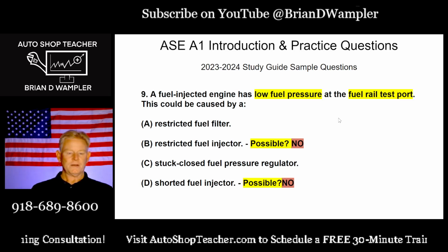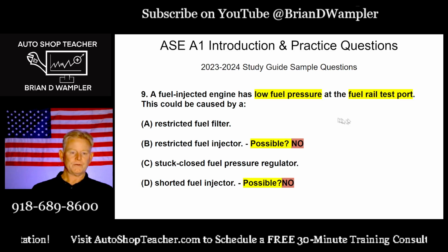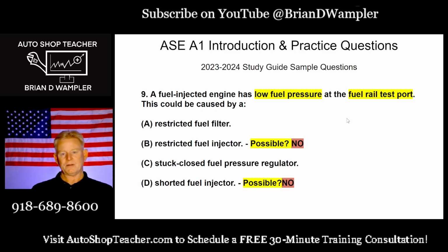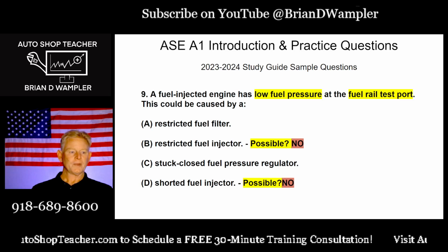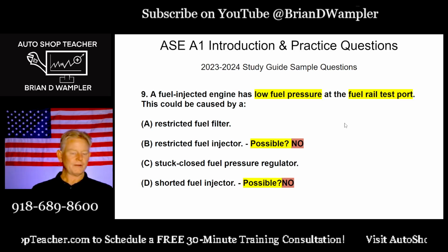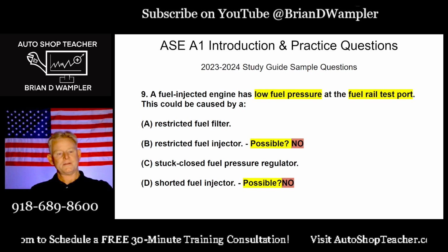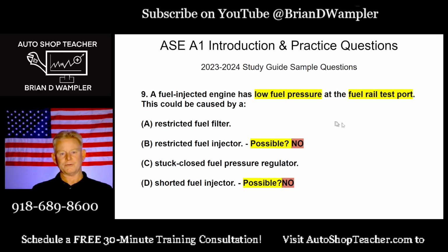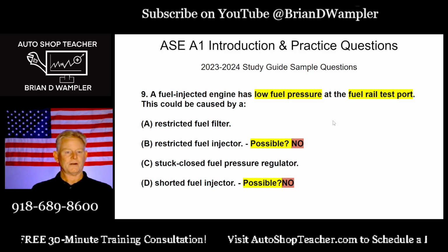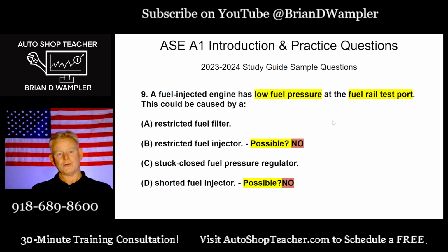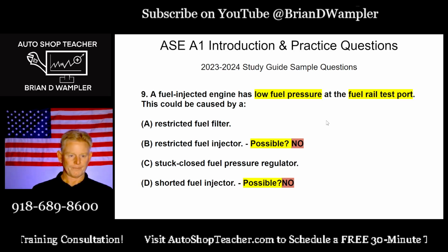That's going to cause fuel to possibly not make it into the cylinder, to the combustion process, but it's not going to cause the fuel pressure, the supply to the whole fuel injection system, to be low. Okay? Shorted fuel injector, I already let that one out of the bag. No, it's not going to cause the fuel pump and fuel supply system to have an issue because a fuel injector is shorted. You might have a blown fuse or some other symptom or condition, but it's not going to directly affect and cause just low fuel pressure. Remember, it doesn't say no fuel pressure, it says low fuel pressure.